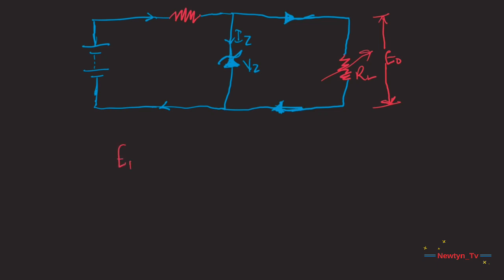So let's first put this condition down. The voltage across R is to remain constant. So it should remain constant at 12 minus 7.2, which will be 4.8 volts, as the load current changes from 12 to 100. Okay, now the minimum Zener current will occur when the load current is maximum, right?